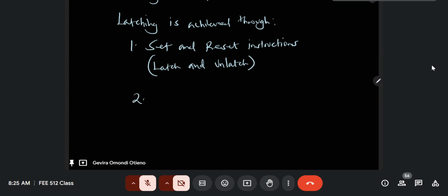The other method that can be used to achieve this latching, where the output is changed to a state of true, then you hold on to that state until a certain condition occurs, and then you return the state back to false, is known as latching logic. Other books will call it a hold in logic. So these are the two main methods of achieving latching.